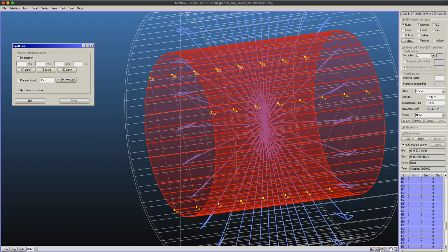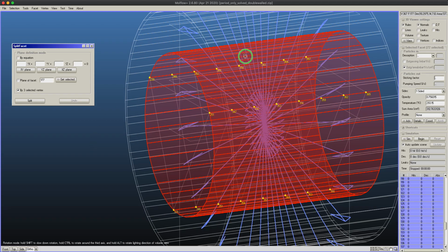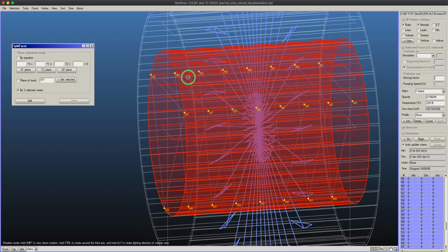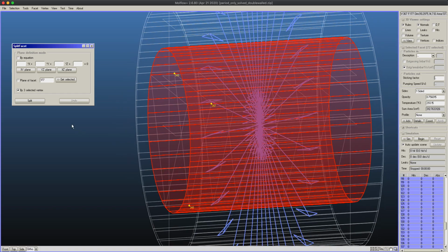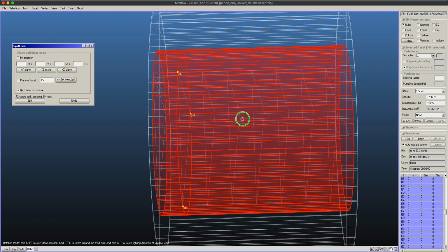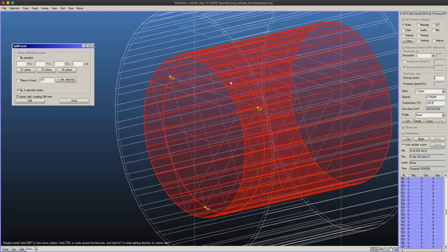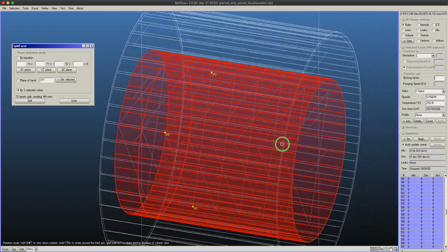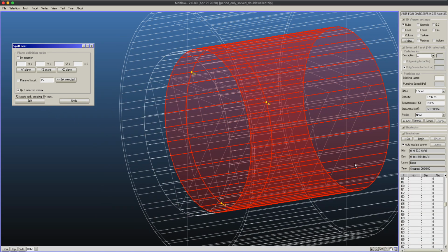To select vertices, you either click on this vertex selection mode. Now I've got a V letter next to my cursor. Or you can press the tab key, and then it says tab key down, facet vertex selection mode swept. This is easier for me because in this case, I first select the first cutting plane. It's relatively easy. I ask it to split. I turn off the normals. Now I can see that the splitting already happened. And now I don't have to leave the selection. I just press the tab key, select the next splitting plane, and click split again.